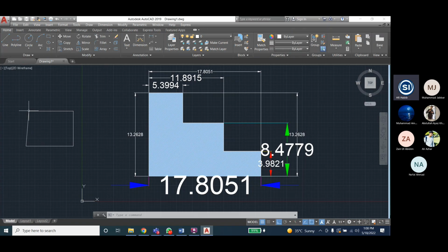So now if you again apply the hatch command and pick point and select this, it is selected. Press enter and you can change the style from here, like this style, any style. Gradient, any style, for example. Color. So in this way you can change.